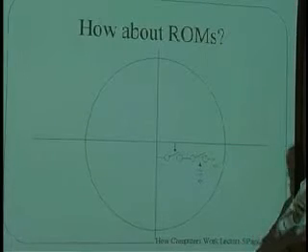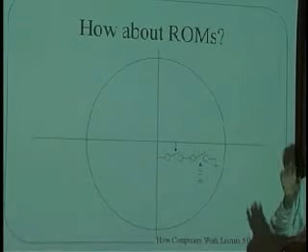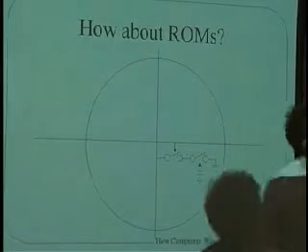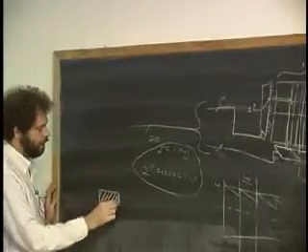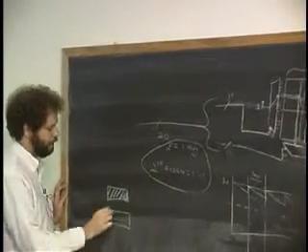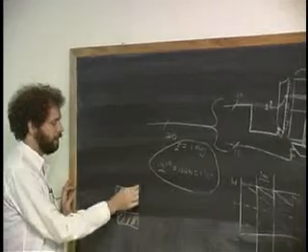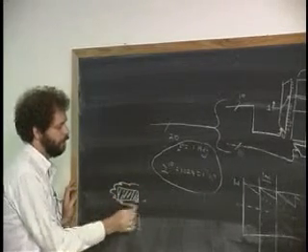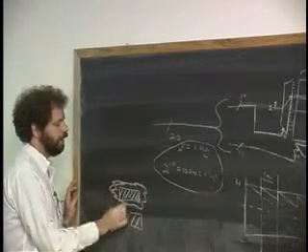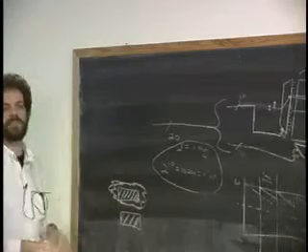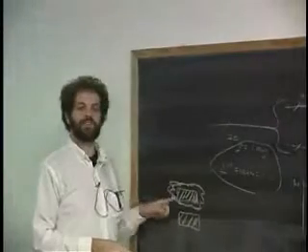of silicon dioxide. Totally isolated, okay? So there's a piece of semiconductor which can conduct electricity a little bit, and another piece like this down at the bottom. And this piece is totally enclosed in 3D in glass. It's actually grown on the circuit like that. And it either has charge or it doesn't have charge.